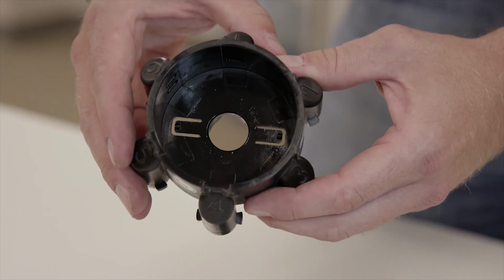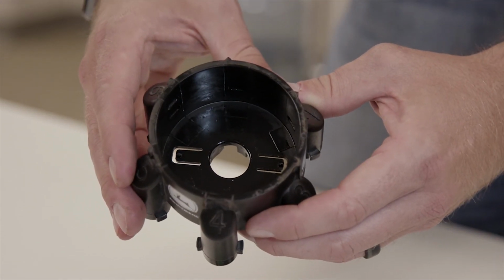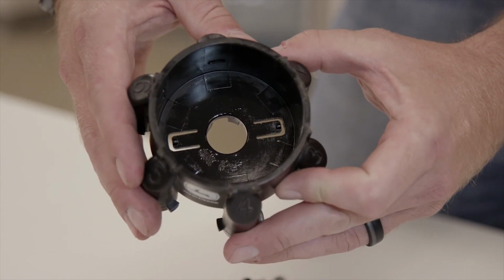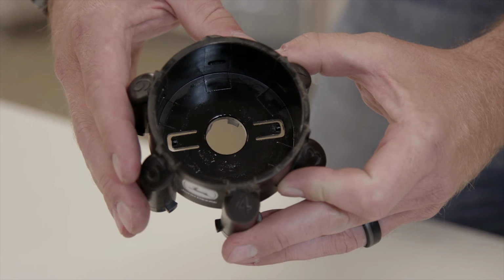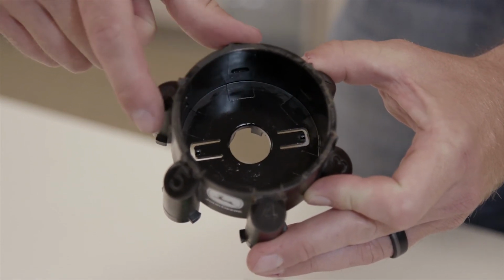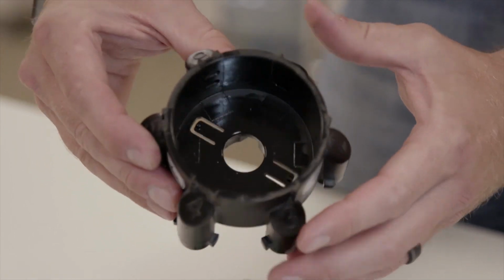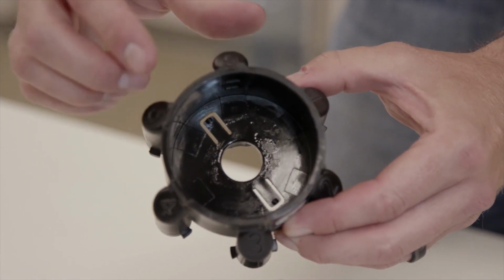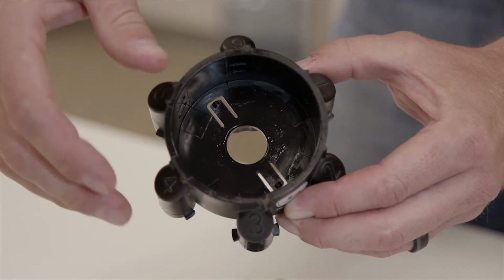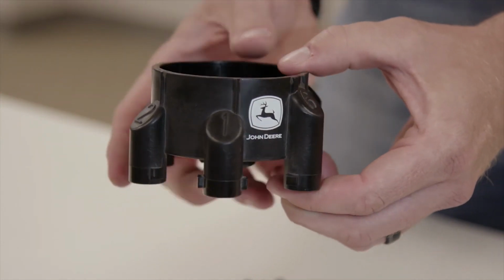That basically means that when position number 1 is in the front and 4 is in the back, we're sending flow to the number 1 position with the A PWM and flow to the number 4 position with the B PWM. When we rotate and have number 6 in the front, number 6 has 2 portholes, and that's going to provide flow from both the A and B PWM, providing us our 30 Hz pulse out of one individual nozzle.